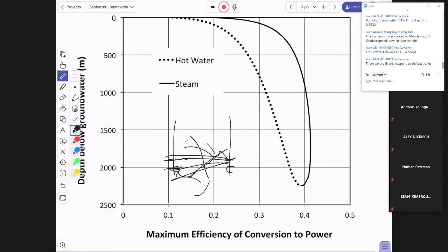They create the same as fracking. And so they inject under really high pressure. So the pressure is greater than the weight of all of the material above it. And if you can lift that up with the pressure of the fluid, then that fluid goes in and they put in a gel that's carrying sand with it that just keeps those fractures open. Okay, so that's all fracking, and that was what was causing the problem. I wouldn't even be thinking about doing that. There's no need to, because steam operates differently.